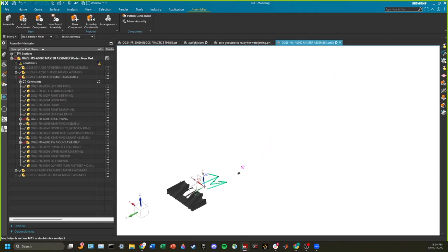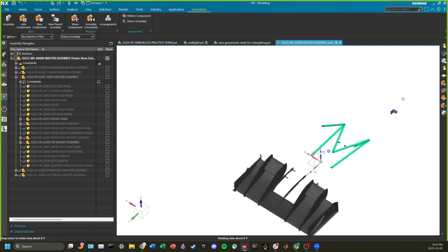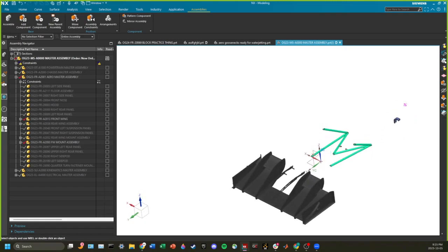Here's an example of wave geometry. So in order to make references to your components where you're basing off their coordinates in the grand scheme of a whole assembly, instead of saying I want to import the entire chassis, you can wave geometry link, which takes a fake one, and it brings in the things that you need.